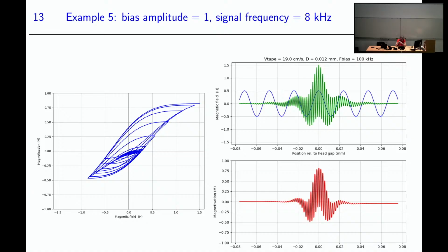Now, this is, if the bias signal, for example, is 100 kilohertz, which is typical, and in a digital system, you would need a sample frequency of something like 1 megahertz to do this correctly. That means you need a few hundred evaluations of this nonlinear function, which is quite complicated. It's not just nonlinear, it has this hysteresis. So that's quite expensive.